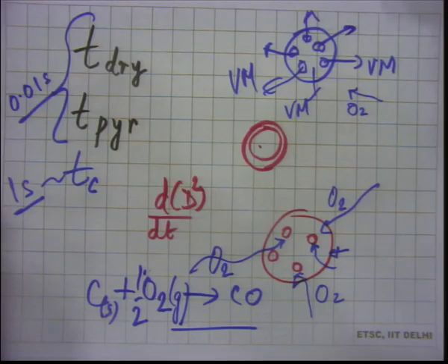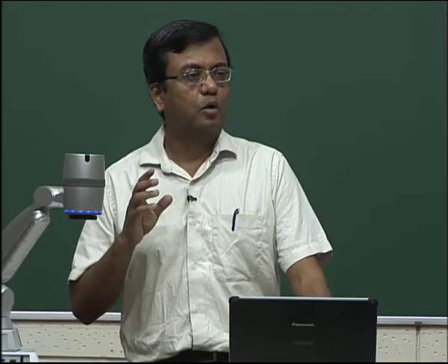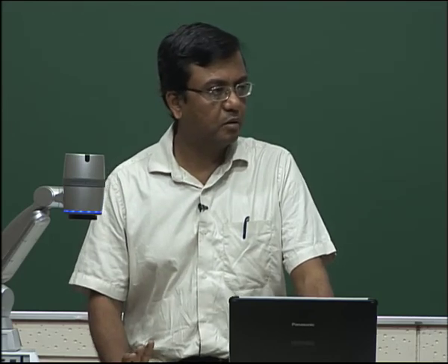The mineral matter, which is dispersed throughout the char in small nodules, mostly less than 2 microns in size, becomes molten, and trace metals in the mineral matter volatilize. Then many molten mineral matter nodules agglomerate into a few nodules, and toward the later stages of char burnout, the char may fragment into several pieces. Coal also has mineral matter.